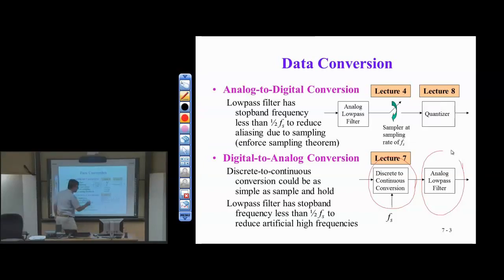All right, so again, our goal here is to take some discrete time signal, and it's also digital. It is quantized in amplitude, and we'd like to produce a continuous time waveform that looks like what we might have started with in analog to digital conversion. But our conversion is only good to what range of frequencies? Fs over 2. So when we sample, we're going to capture frequencies up to half the sampling rate. That means that when we're in discrete time and we want to reconstruct, the best that we can do is frequencies up to half the sampling rate.